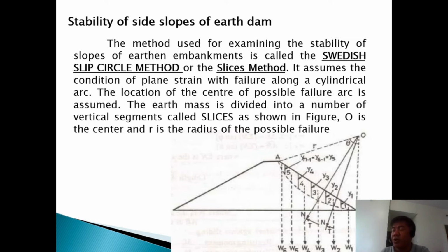Why? Because here you are looking into the weight. If you remember when we took our hydraulics subjects in college, we just analyzed in terms of the overturning and the resisting moment, and dividing them, we computed the factor of safety, and that's it. Here it is different because it involves both the water resources aspect and the geotechnical aspect, which includes the behavior of the soil.